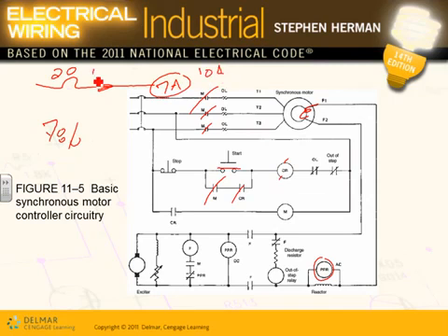You're pulling 10 amps, but you're only using 7 amps of them. What happened to the other 3 amps? They sit there and magnetize the system. So they're creating more voltage drop problem for you because you're pulling more current than what the load needs to compensate for the low power factor. That's the problem, pulling more current than what the load needs. The other current is just sitting magnetizing your system, so it creates a voltage drop problem.